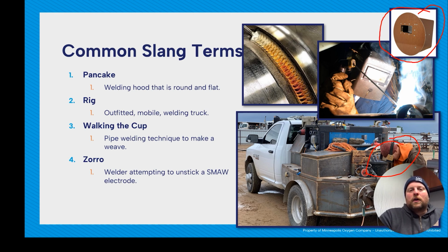So if you're welding using this, you just got to make sure that you're not having UV light bouncing off and hitting the parts of your face that's not protected, because we don't want to do that. But yeah, great choice for those of you who are working outside and working on pipe, and you're really welding all day, where you need something that's lighter and just allows you to move better.